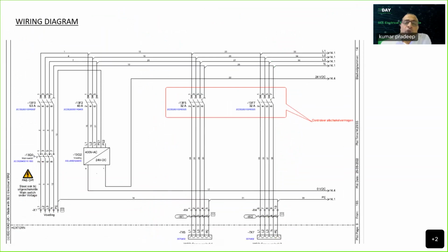So let's look at some of the outputs which this software generates. So this is the simple wiring diagram, and the red line here is what we talk about, the redlining, where you can add some comments to it. You find the numbering which are auto numbered already, which are the phases and which are the circuits. This arrow goes the cross referencing. If you double click, it will go to the 14th page, 4th column, where this line will continue.